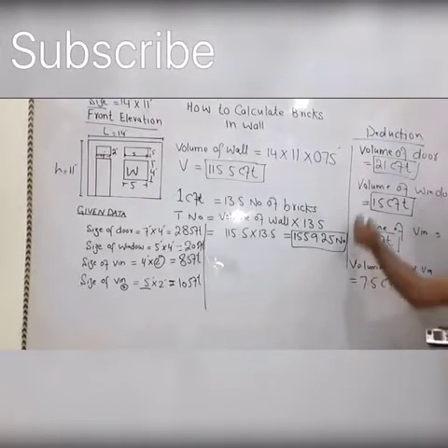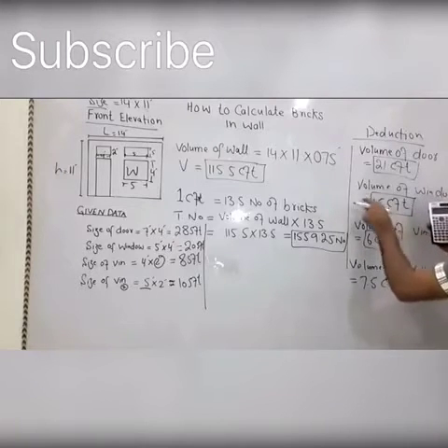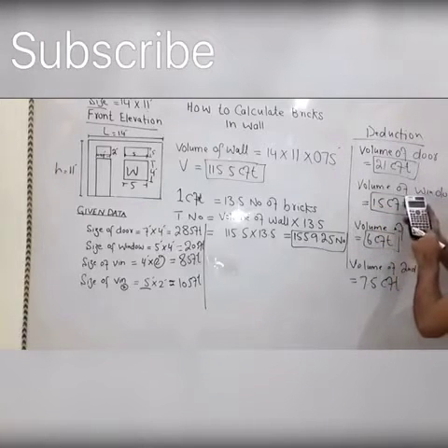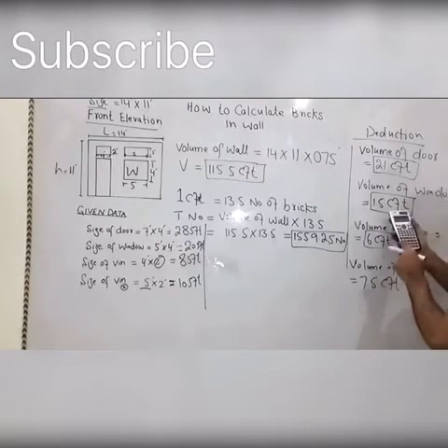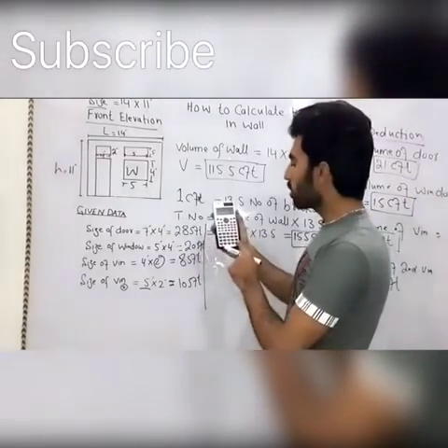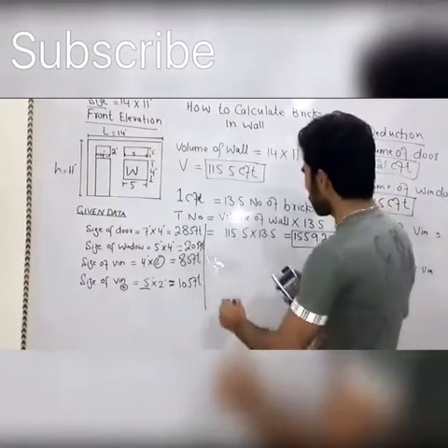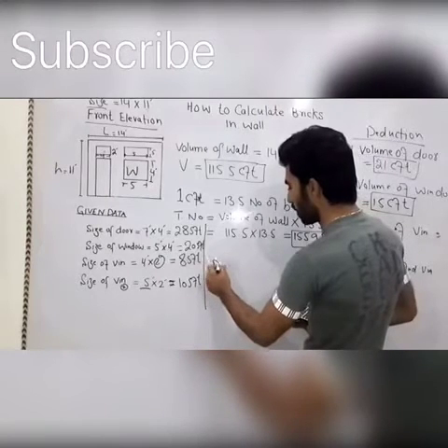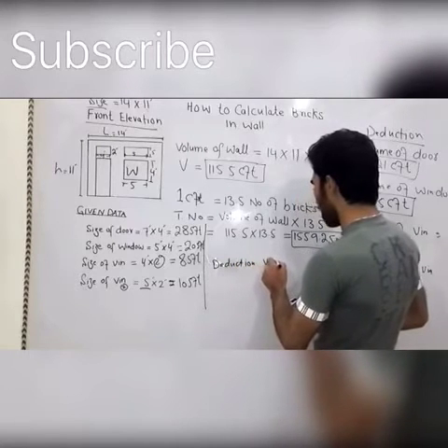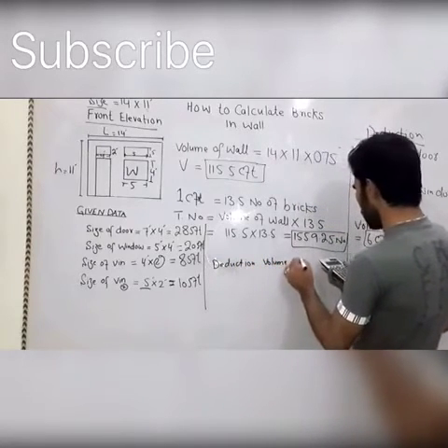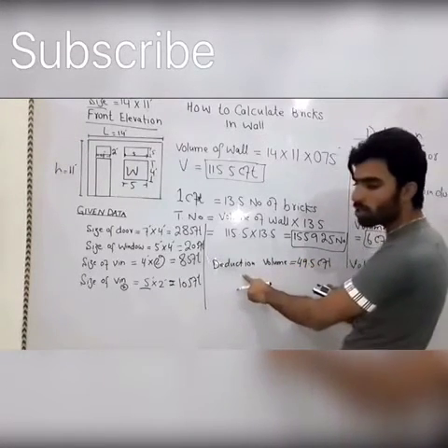Okay, so now you can add all these, which are 21 plus 15 CFT plus 6 CFT plus 7.5. Okay, so it will give you the answer 49.5. So the deduction volume is 49.5 CFT. Okay, so how many bricks will be deducted?